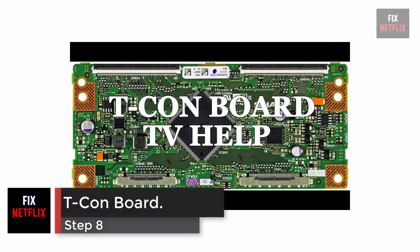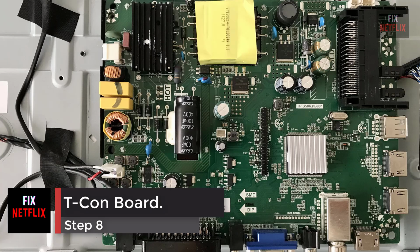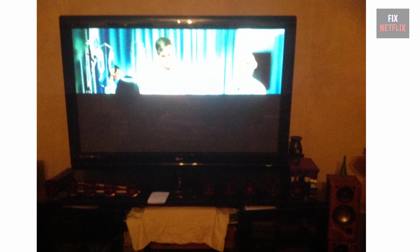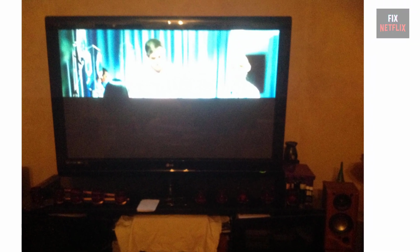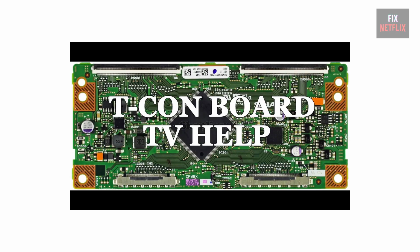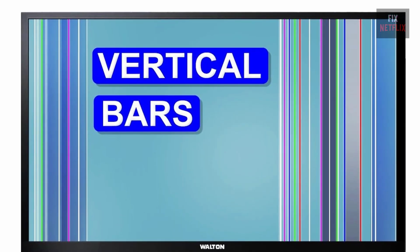Step 8. T-con board. This check for the T-con board also touches on the condition of the main board. Note that problems that show up on half of the screen, like bars or such, point to a failed main board, as T-con board errors show up on the whole screen. As an example, if an error like bars is on the whole screen, it is likely the T-con board.